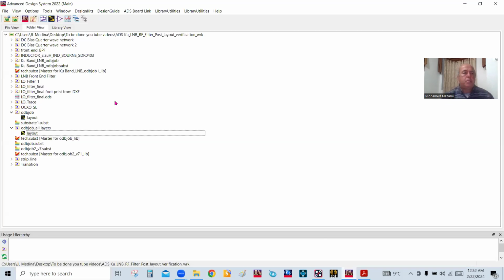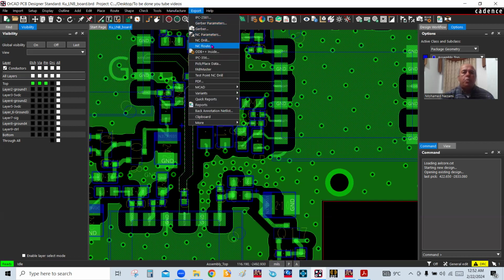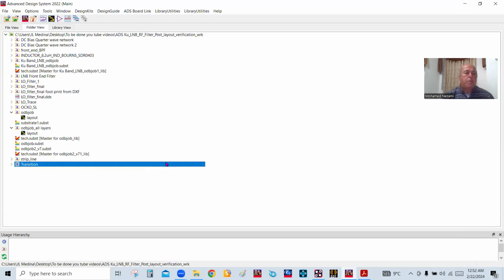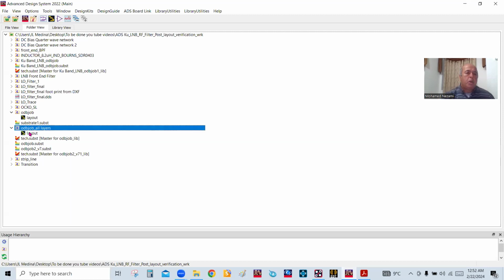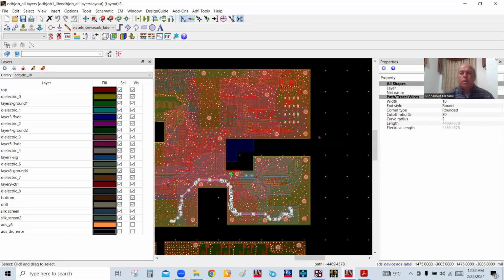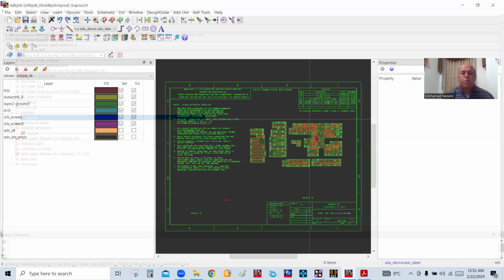So let's go back to ADS, and as you recall, what I did basically is we go to this and we export the ODB++ on this, and it gives you the board in a portable form that you can import into other packages, and that's what I did here. So I imported this board, and this is what we got here.